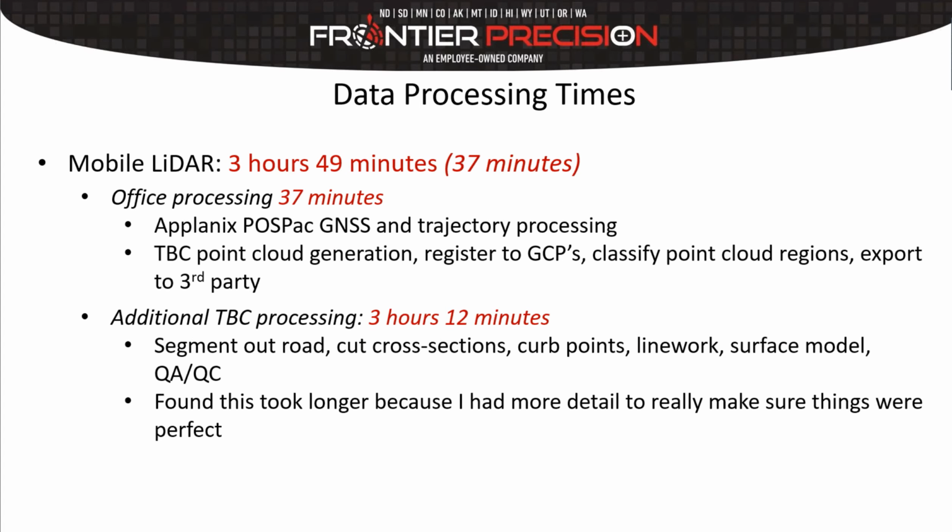Okay, lastly, moving on to mobile LiDAR. So the processing time here, start to finish, was 3 hours and 49 minutes. And then to get it out to third party was 37 minutes. So the steps involved in that were processing the trajectory and the GPS in POSPac, bringing it into TBC's mobile mapping module and running the point cloud generation. They have a nice mobile mapping ground control registration process that we used in there, and then classifying the point cloud into regions and exporting it out. You could bring it into, say, InfraWorks or something like that.